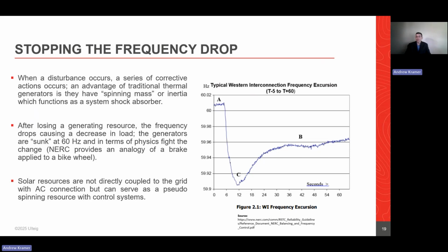It's not. It certainly can help, but it's a little bit more of multiple steps through power electronics, through how it actually helps during disturbances, and how we potentially use the inverter with these things as well. So again, just keep in mind that synthetic inertia is not real inertia, and that's why a lot of times we like these spinning masses. They have a lot of value from a reliability perspective.